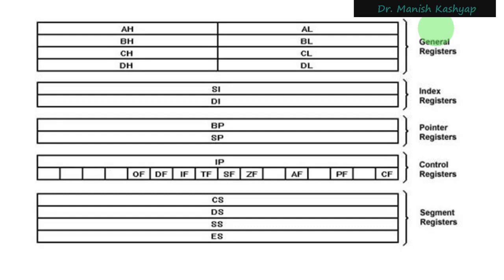Here the result will be stored in the register which we specify, right? So in that way this accumulator is a little bit free compared to 8085, but it is still called the accumulator because for some default calculations it is still used as the default register, but not for all calculations as it was in the 8085 microprocessor.